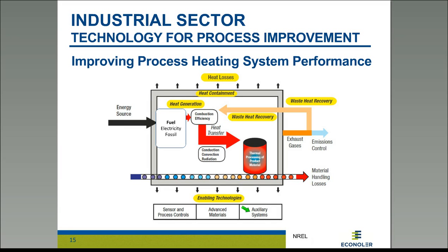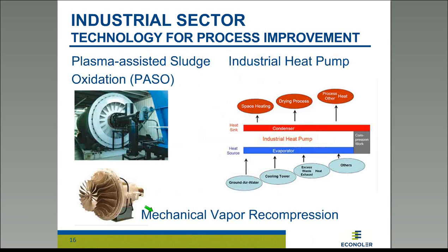And not only energy saving. I remember that for an aluminum plant, one of the problems was the sensor was failing so rapidly in the molten aluminum that basically the oven was controlled manually, and it was overshooting very often the target temperature, which resulted in loss in production for this plant. So it was possible to design a new sensor that was just intermittently measuring the molten aluminum temperature, then getting out of the molten aluminum. And this allowed us to resume an automatic operation without overshoot of the oven. And again, it was resulting in very large savings for the plant.